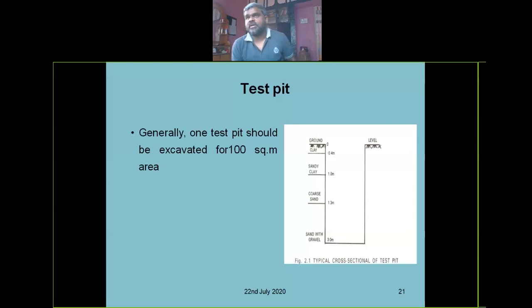For example, for the Hyderabad Metro project, at the location of every pillar, every abutment or every pier, a test pit has been taken, right?